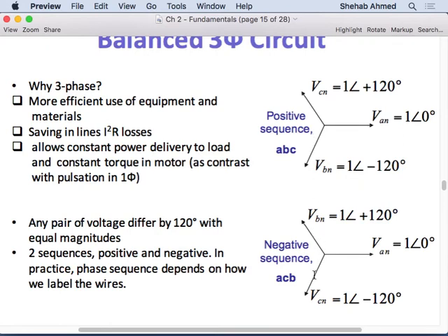If you have both positive sequence and negative sequence in your supply, it's like having the motor spin in one direction and also having it spin in the other direction. So what is that doing? That is adding current into the motor that is not providing extra torque. That is actually providing opposing torque. You want to spin it in one direction and you want to spin it in the other direction. So the sum will be the difference between them. You will be putting in current from positive sequence, current from negative sequence, but the torque will be less. So you're just burning power in the motor.